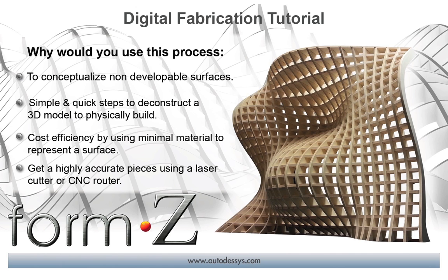And if you're asking yourself why would you use this process, you would use this process to conceptualize non-developable surfaces. And as I said earlier, these are the type of surfaces that can't be bent or folded out of a physical object. So it's a very quick and simple method to deconstruct a 3D model to physically build it, and it's a very cost-efficient process because it uses a minimal amount of material to represent an idea in a surface. So you also get a very high level of accuracy by using this process to lay out the pieces to be able to use a laser cutting machine or a CNC router. So try this process for yourself to see what creative structures you can come up with and be able to fabricate for yourself.